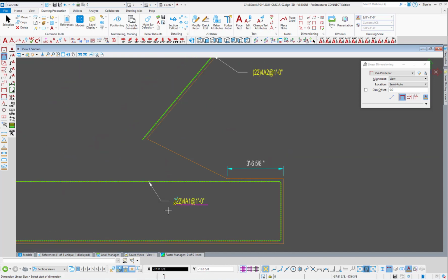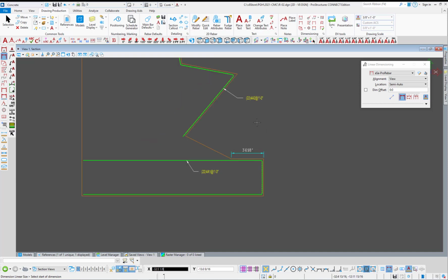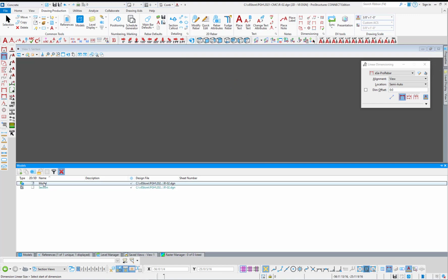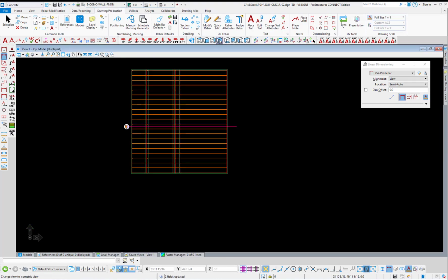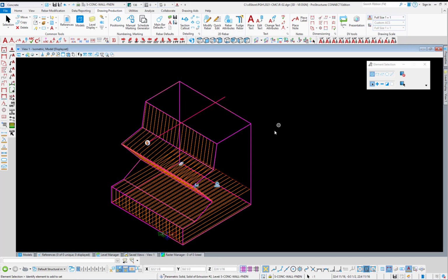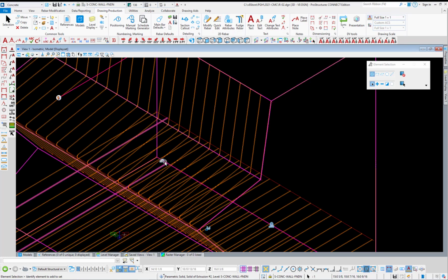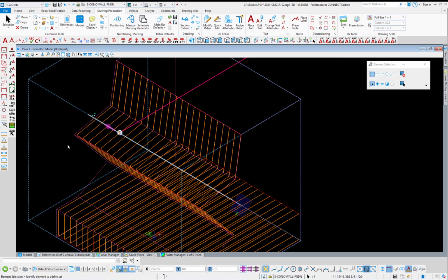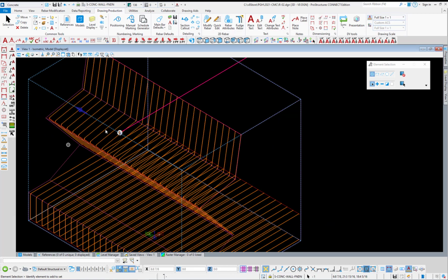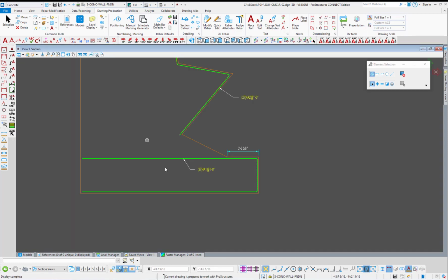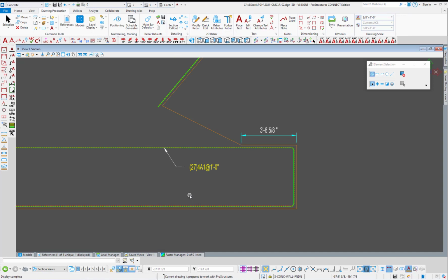And then if you notice, I've got 22 bars here, 22 bars there, 4A1, 4A2. If I come back to the model, again, this is where everything's tied together. Let's just say, for simplicity's sake, I want to change the extrusion. And we'll extend it out again. Added bars in, and then your section cuts will also update. So now I have 27 bars.